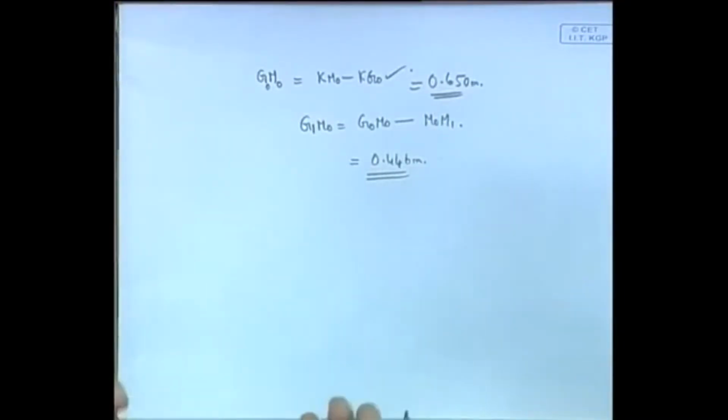If you are asked the final drafts, same thing: you find the change in trim, trim aft, trim forward, and in this case the bodily sinkage, I think it's a bodily rise. Remember, it's not a bodily sinkage, because this P is actually up. When it comes up, it's going to be a bodily rise, not a bodily sinkage.